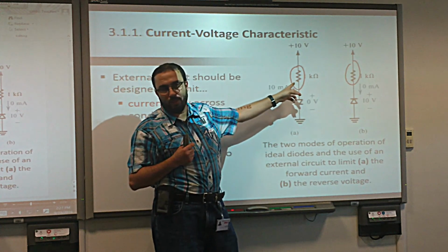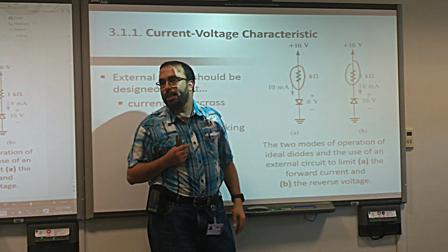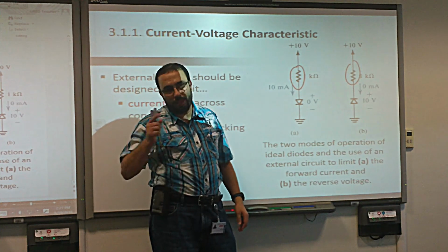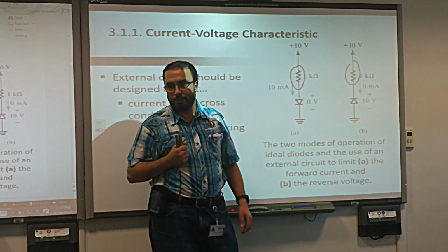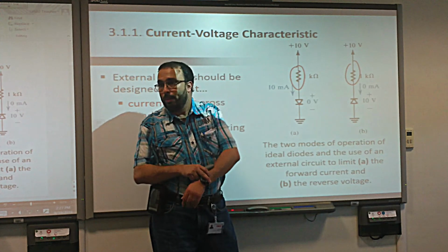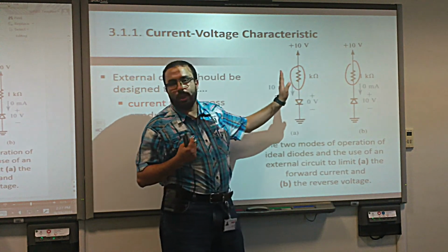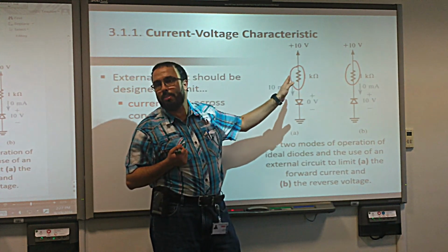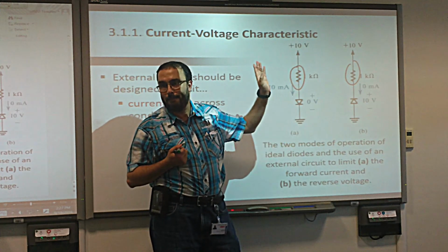If we take a huge amount of current, we'll make the battery die very quickly, and we have to charge it again or throw it away. Do you understand? Good? So always when you deal with a diode, always put the resistor in series with it. This is practical.